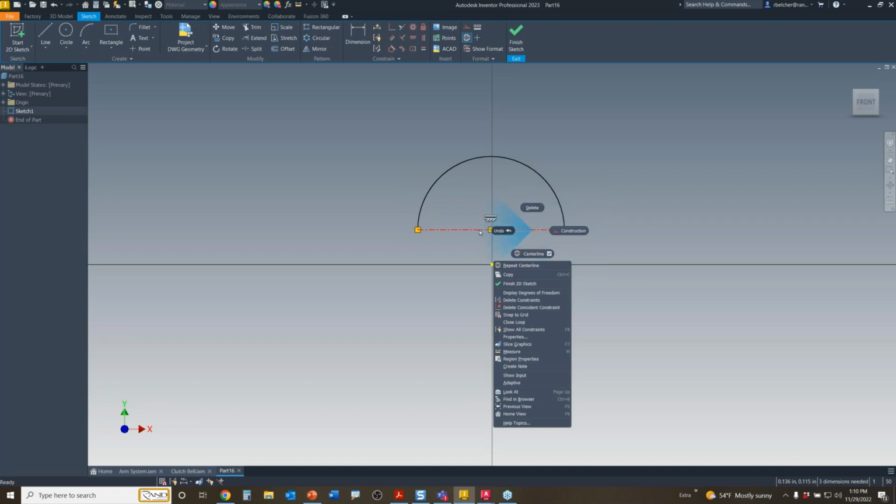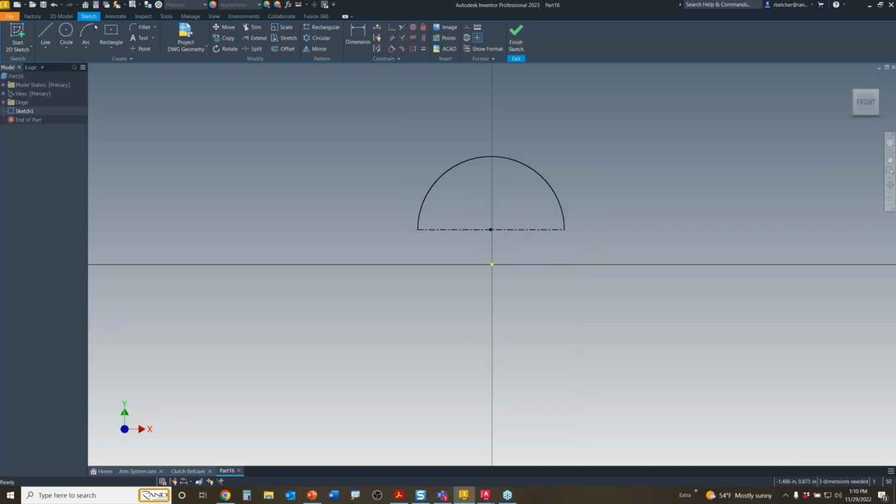And in this case, when you select a line, center line is the straight down version. So the way this works, let me undo and show you again. The way this works is you highlight the line and you right click and drag in the direction of the little command that you want to use. So by using the right mouse button and dragging, I can make that center line so quick.